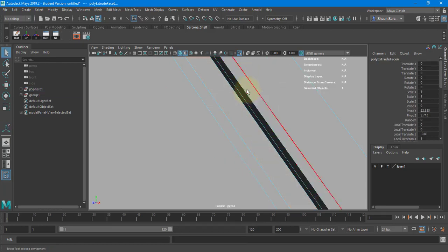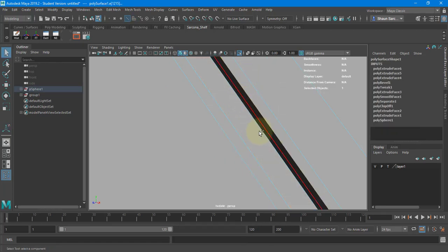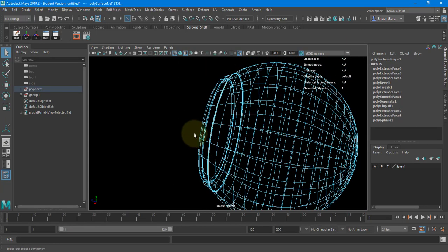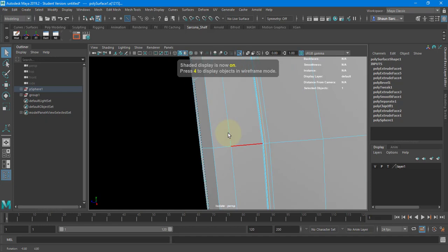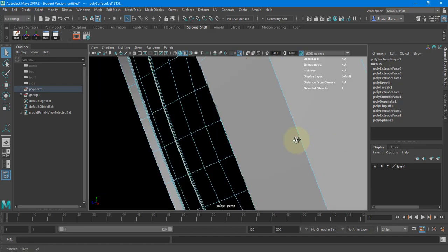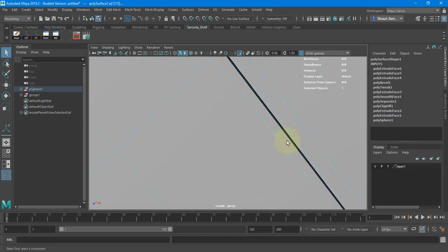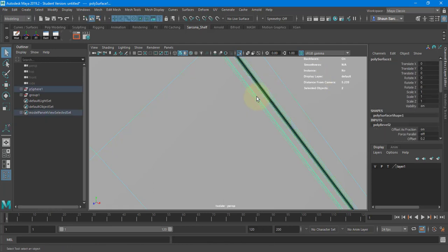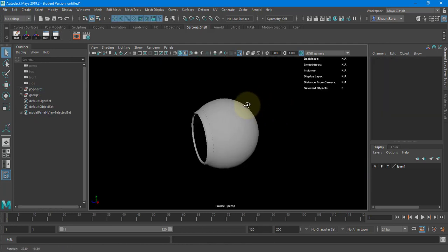And then I'm going to go to my edges, and I'm going to double click that one. I'm going to go to wireframe. Sometimes you have to select things in wireframe. I don't know where I went. Go back to shaded mode because I lost it. There we go. Double click that. Shift double click that. And shift double click that. Okay, so super tiny. I'm going to add a little bevel to that. And 2 segments. Back to object mode. There we go. Okay, now you can barely see it.